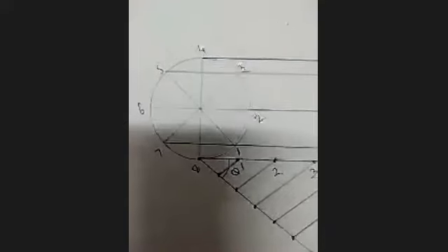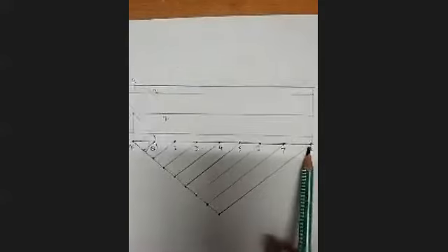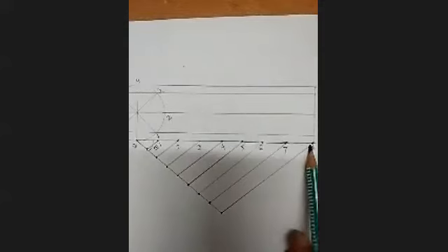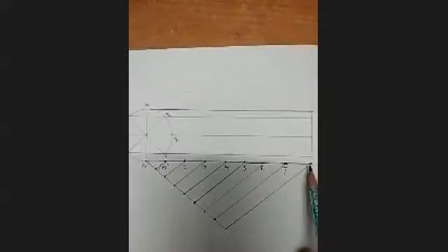See, the circle which you have drawn is divided into 8 parts. We have taken this line, the baseline, from this bottommost point. That length of line is pi d. Then we have divided this pi d distance into 8 parts with equal spacing by following this construction method. Then from each point of circle, we have drawn the horizontal line, this line, the next, then this one, and final. And this is the final position of the circle.